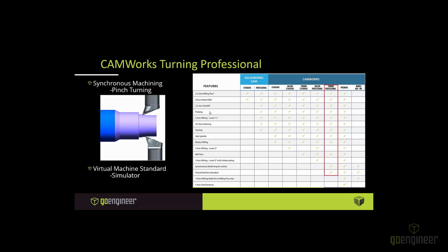On more advanced lathes, you have a secondary turret, in some cases other turrets. You can have more than 2 turrets, but you can have another turret mounted down below, kind of in the front of the machine, near your feet. You'd have one tool, perhaps loaded in the upper turret, doing a roughing pass, and just behind it, on the bottom side, the secondary turret is following with the finishing pass.